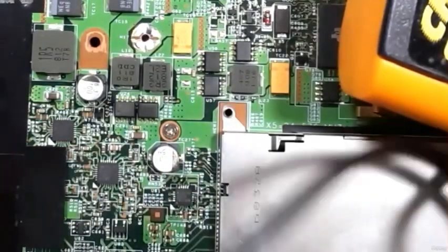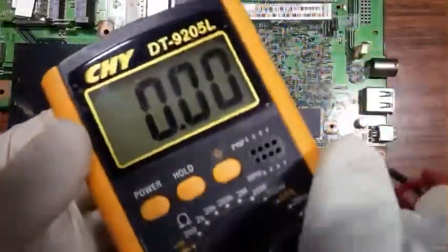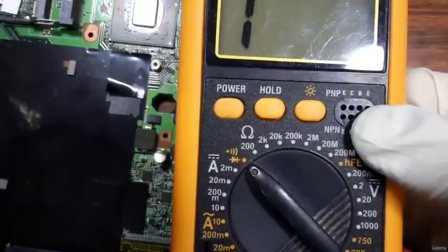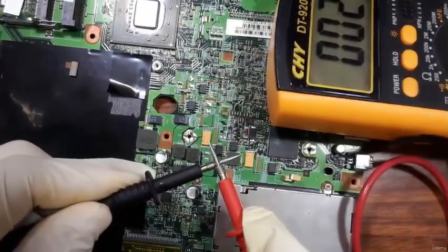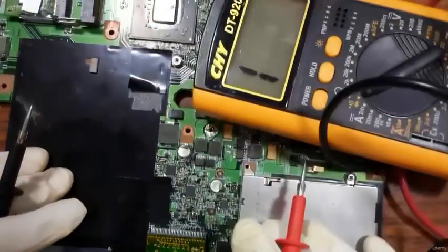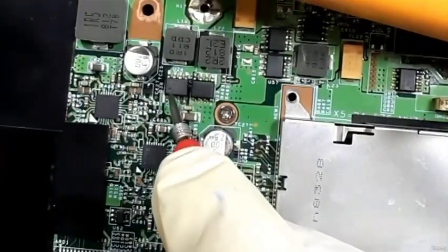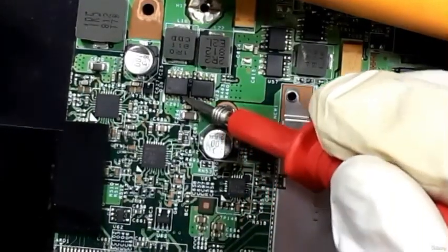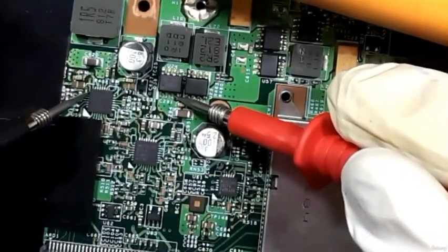Easy. So let's first unplug the adapter and put the multimeter to the buzzer option. Okay, let's check if we set the continuity correctly. Okay, let's check which one of these ICs is responsible for controlling this MOSFET. So easy, you should just go to the gate of one of these MOSFETs. So put one probe into the gate of one of these MOSFETs, okay, and check this IC.